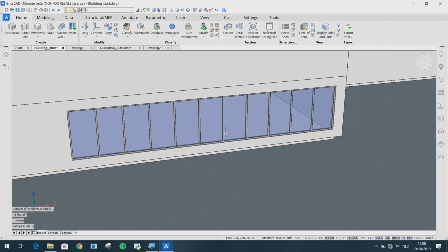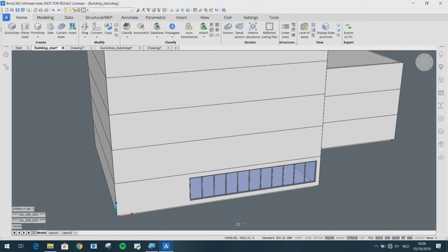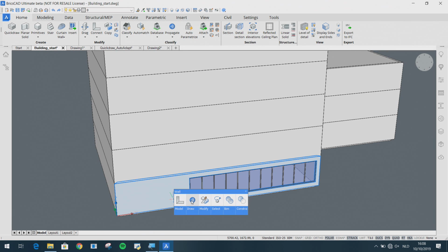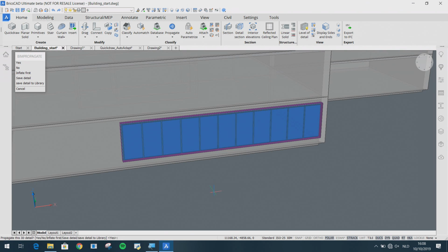It will transform this grid into a frame for the window and the glazing included. And now, it's an intelligent window, we can reposition it using the window dimensions to fit exactly where we want it to. Now of course this is only one window, we want multiple windows, we want windows on other sides of the building as well. We could recreate this window, or we could try to copy and move it around and reinsert it.